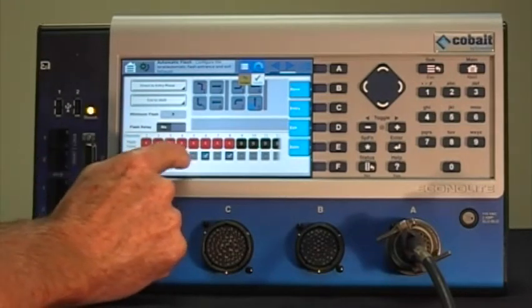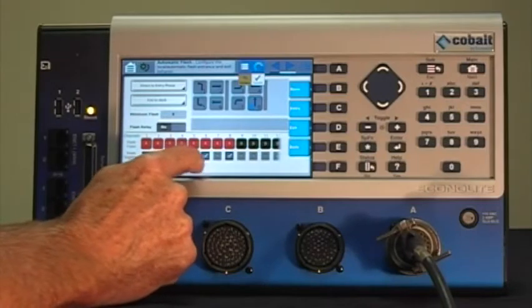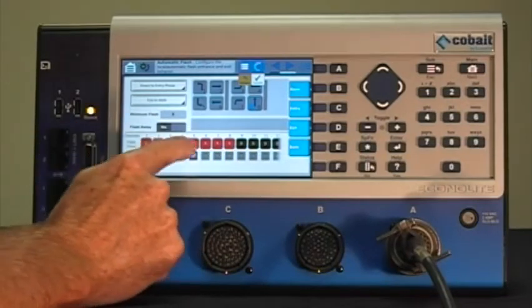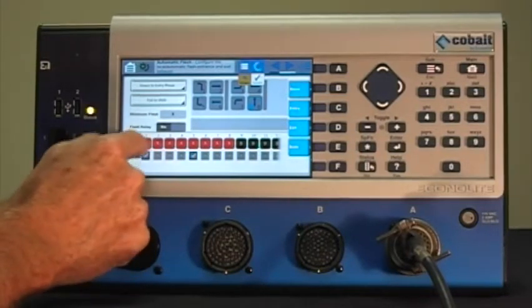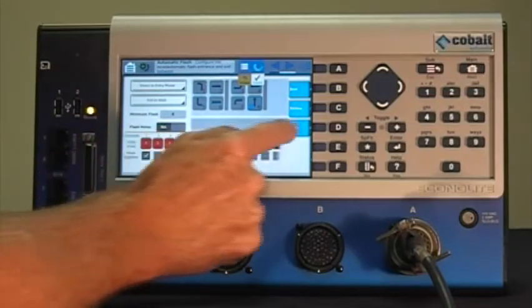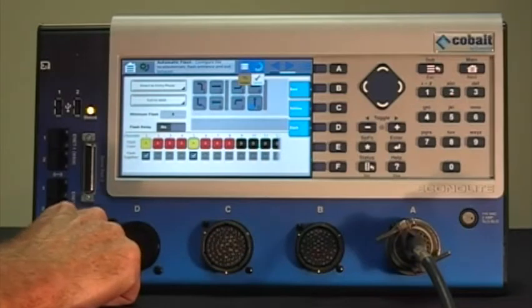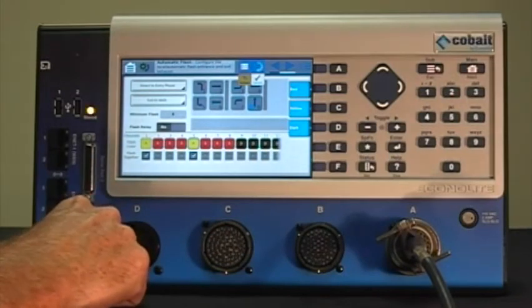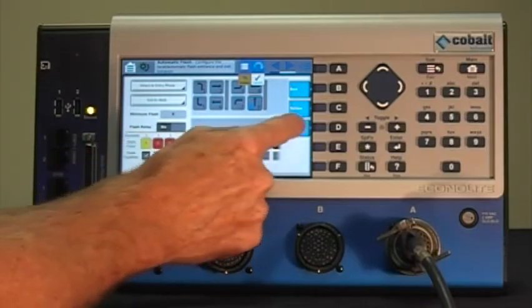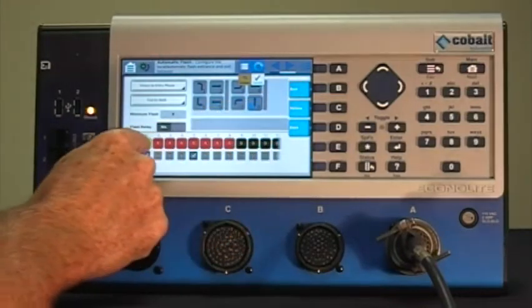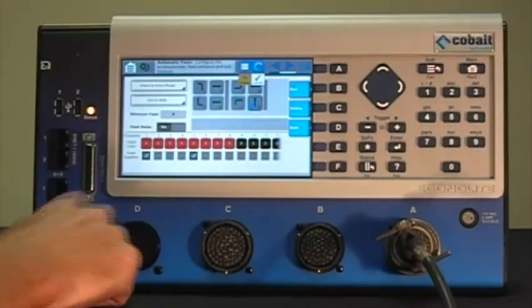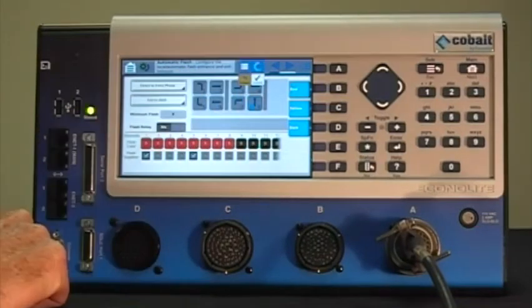So I'm going to turn off those and set 2 and 6 to flash together. And if I wanted those to flash yellow, for instance, instead of red, in our T intersection it might be safe to have those movements flashing yellow, or put them back to red. Let's commit those changes.